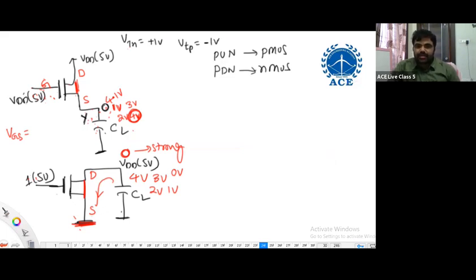Yes. So similarly, if I use a P channel MOSFET in the pull-up network, let us see what happens. Finally, what we are understanding here is that the N channel MOSFET can work effectively in pulling down. In pulling down, the output node is pulled to logic 0 perfectly. That is the reason the pull-down network is constructed using N channel MOSFET. If I use an N channel MOSFET in the pull-up network, it has a problem. That's what I discussed. Similarly, let us understand P channel MOSFET functionality.